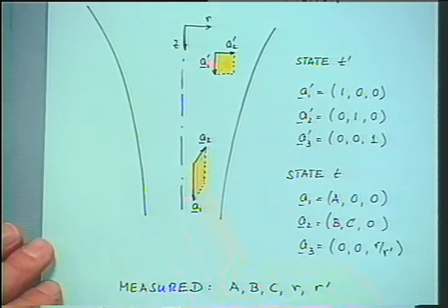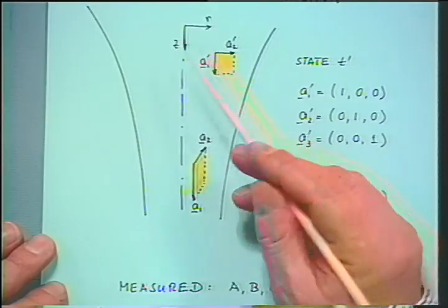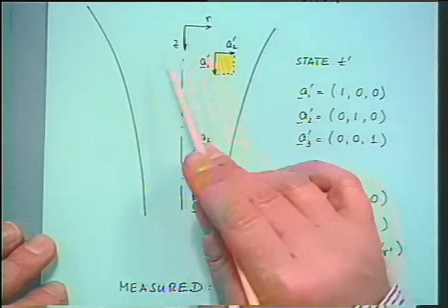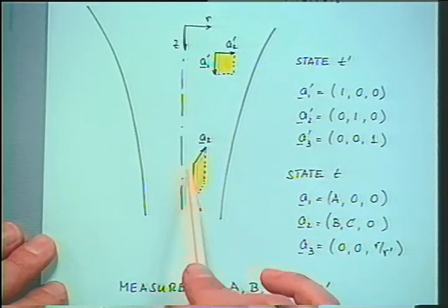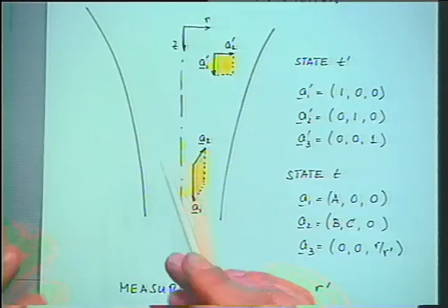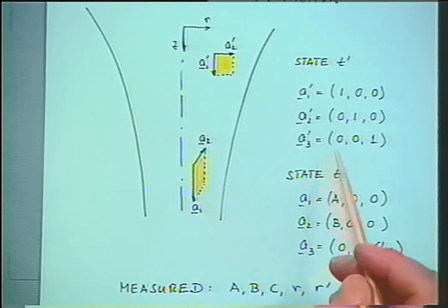Now, it turns out that A3 is very easy to get. It's associated with the radial position. It's associated with the ring element here, and as the radial position changes, the hoop length is decreasing here, for instance, and in this case, A3 is shrinking. So we should measure the radial position to get A3.